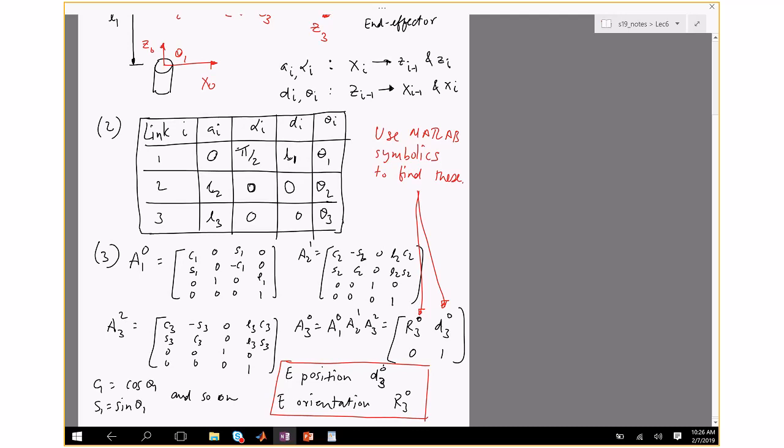give you some practice. Drawing a manipulator using Matlab. The key thing is a command which you've probably used in your animation. It's called line. So if you're given coordinates of 2 points in 3-dimensional space, for your homework you only did 2 dimensions, you can take 3-dimensional points and join them by line. That's all you've got to do. So we'll use a command called line.